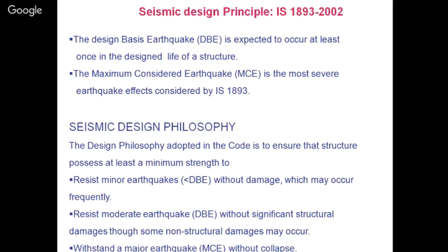for design of structures, but MCE can also be considered in case of very critical structures, or depending upon the situation for what you are designing. If you are designing for a heritage structure or for a nuclear reactor, again the things become critical and various parameters are considered. Keeping that in mind, you can decide whether you are going to consider MCE or DBE.